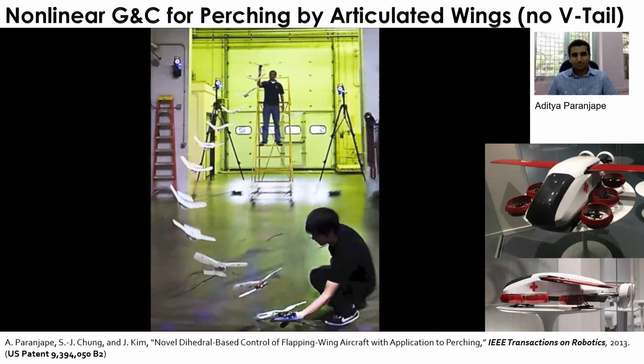One extension of this spectral normalization, and a new idea in Neural Swarm, is that you have to use a deep set, because of permutation invariance. When you have multiple agents, the downwash, or this aerodynamic interaction, is permutation invariant. You don't really care that agent 1 is here and agent 2 is here, so you have to have some permutation invariance. So we use this deep set. The idea is that if you have a deep neural network applied in a superposition fashion, obviously this is permutation invariant, right?